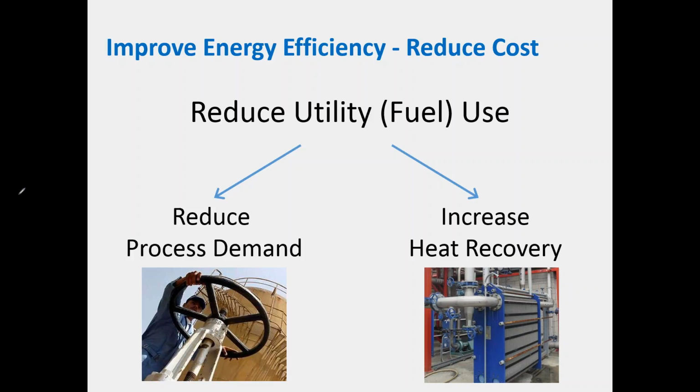But there's opportunities there that can be looked at. Often you're limited, as we mentioned before, if we look at reducing your process demand, often that can be very limited, and you don't have a lot of room to change your process demand by changing your temperatures and your flow rates. And as I said before, there can be other consequences. Maybe there's a yield consequence in some reactor where changing the temperature or the pressure may affect the yield negatively.